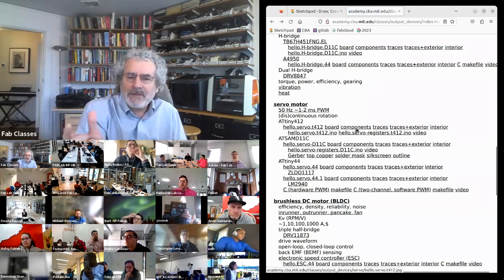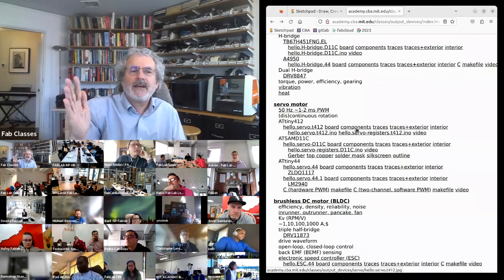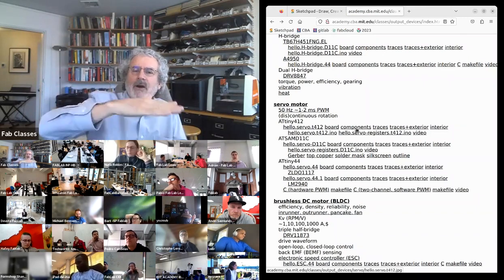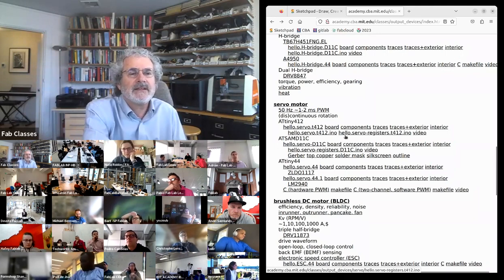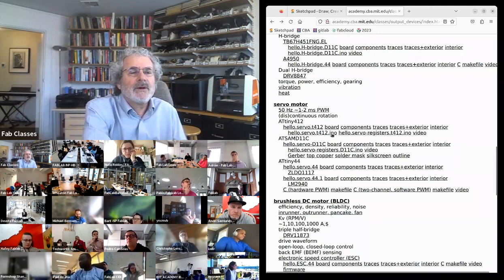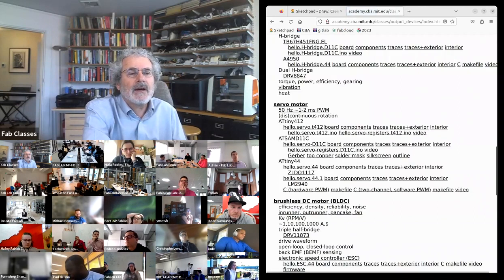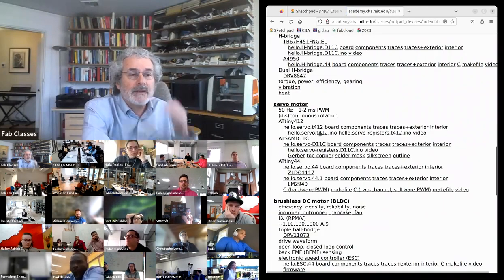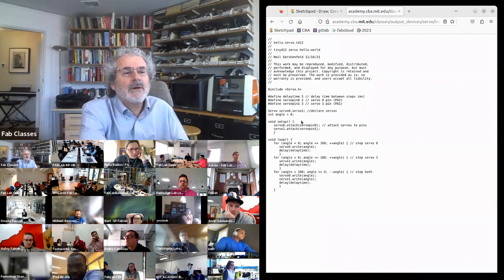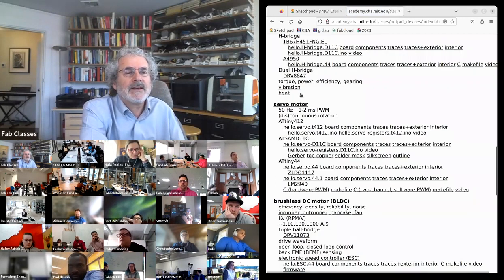Now, the servos are all slightly different. For each servo, you need to check what pulse length corresponds to what angle, but 1 to 2 milliseconds is common. So in this example, let's see, I've got two versions here. So in both cases, I'm spinning it. This is so common that here I'm using an Arduino servo library that makes the pulse width modulation.